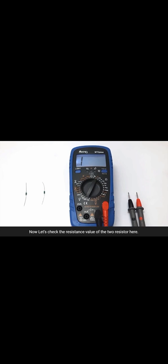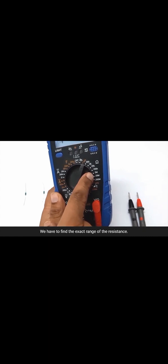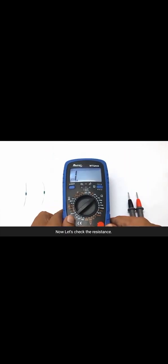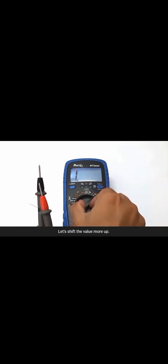Now, let's check the resistance value of the two resistors here. To check the resistance value, I have to switch my knob to the value written here. You may see there are multiple number of values written here. You have to find the exact range of the resistance. I'm switching it to 2K. Now, let's check the resistance. I'm connecting the two terminals to the two terminals of this. It's not showing anything. Let's shift the value more up. So it is 1 million ohms.